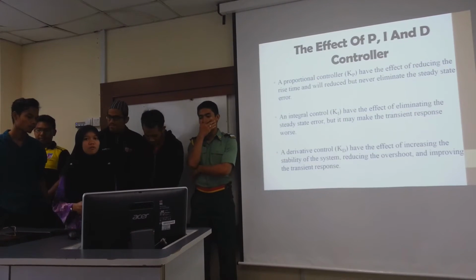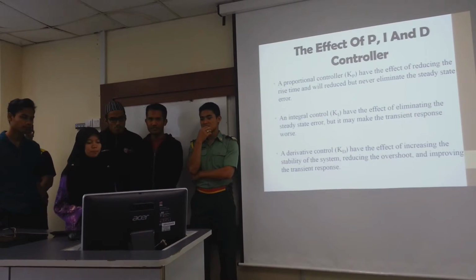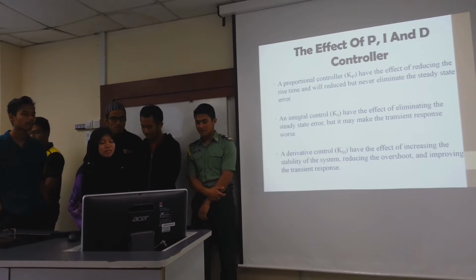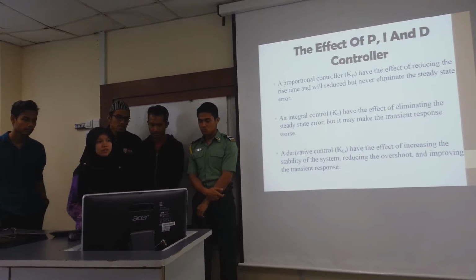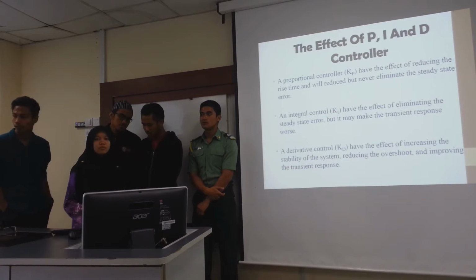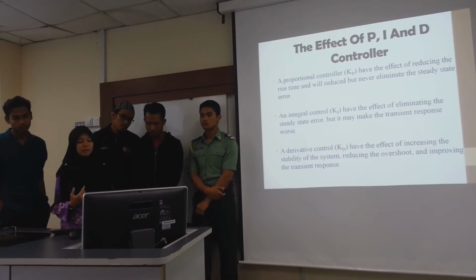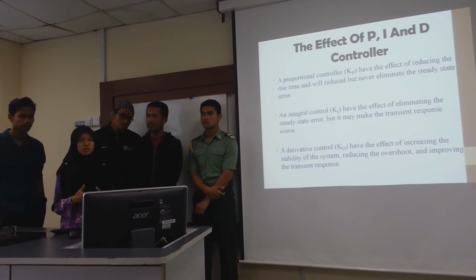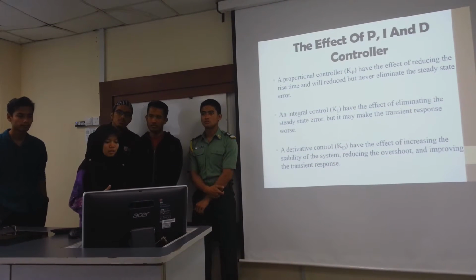Okay, the effect of the PID controller: the proportional controller can reduce rise time, but it will never eliminate the steady state error.